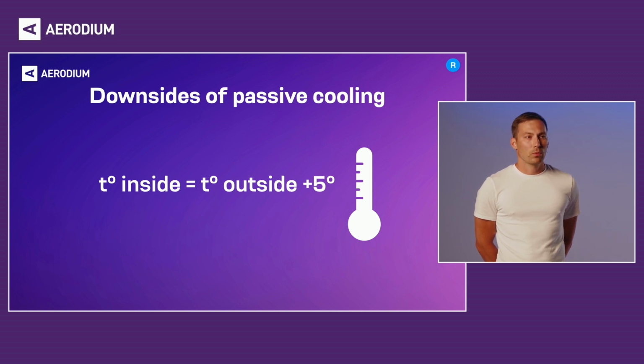So you can easily achieve comfortable flight temperature for professionals, for beginners, etc. Now, when the summertime comes, and now we all see the changes in climate and the temperatures, even in Norway it reaches plus 30 degrees Celsius in the summertime, and in Western Europe it goes up even to 40 degrees Celsius. Now, if there were a wind tunnel in such conditions with passive cooling, then your inside temperature would be even 5 degrees higher than it is outside, because you're not able to exchange all of the air.